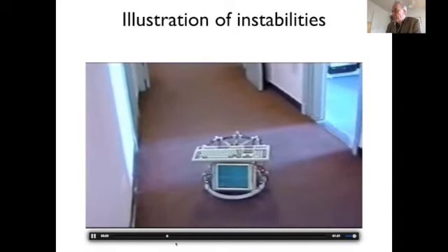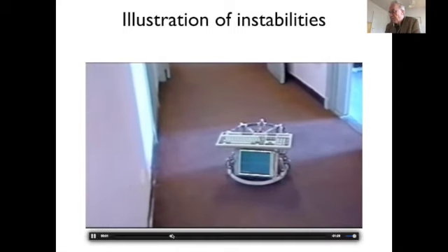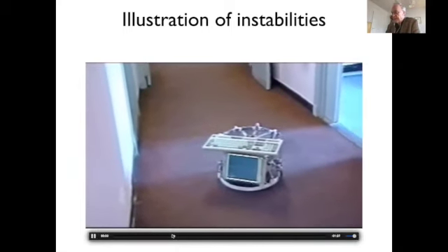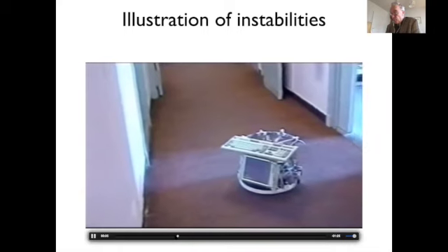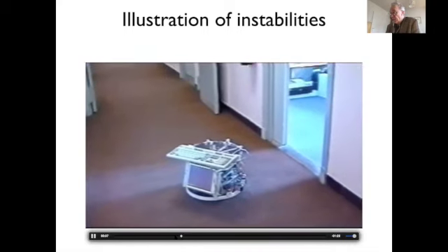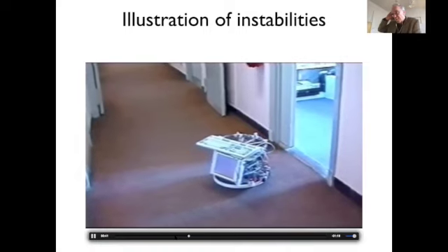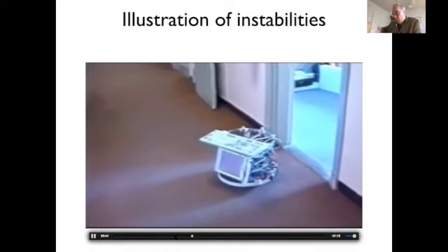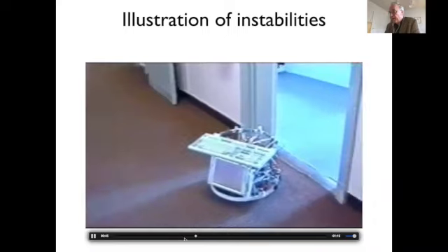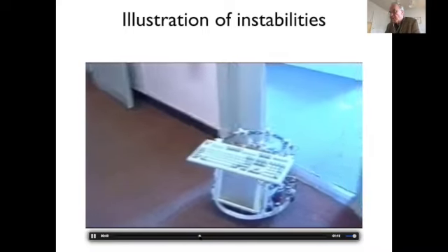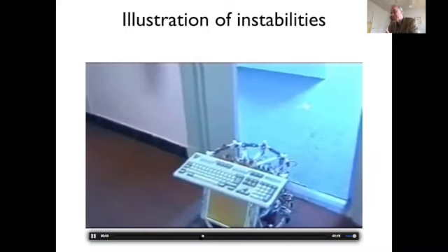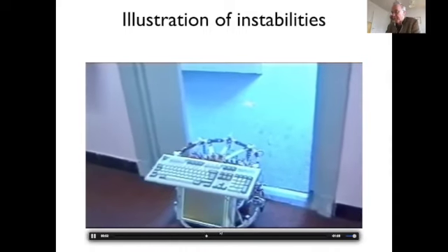And the speed with which the vehicle drives has to do with the integration, how fast we were able to solve the equation on the robot. You can't make the dynamics very fast because you have to numerically solve it in real time. And when you make it slow, then you have to move slowly so that the system has time to reach the attractor before the vehicle has moved a lot.